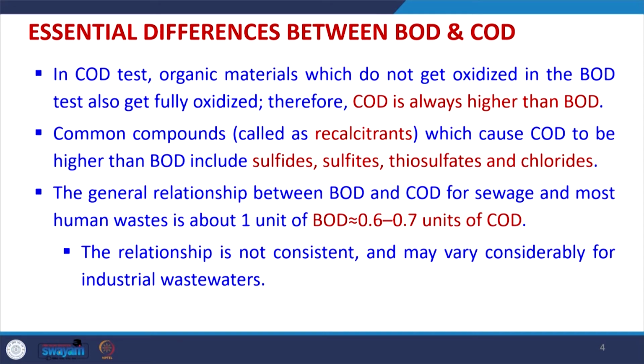So, the BOD to COD ratio gives an idea whether our water sample is easily biodegradable or not. Through that we can select whether we are going for biological treatment or other treatment, physicochemical, thermal treatment, etc. So, this gives a lot of idea. So, how do we understand?